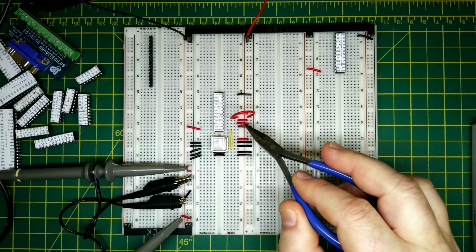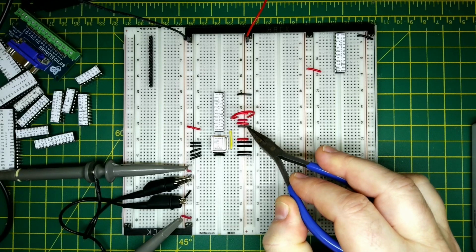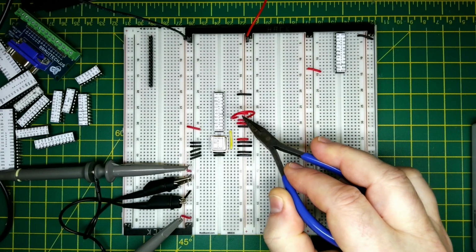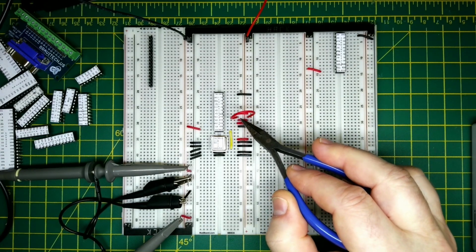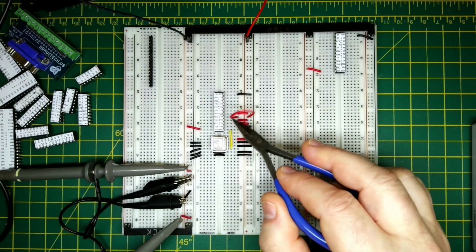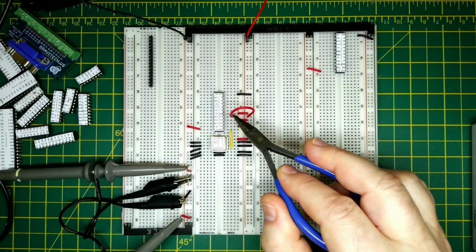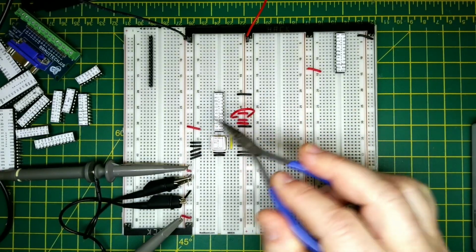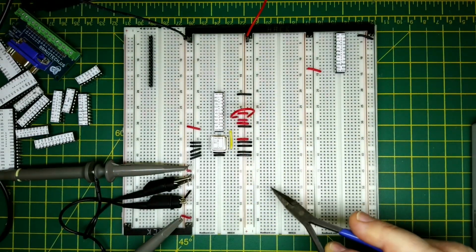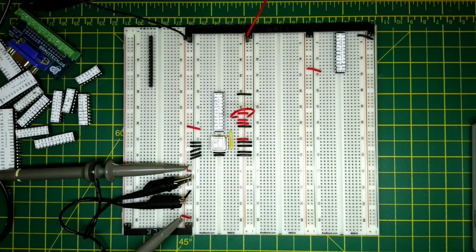One of the outputs is to do with the underline row address, and so what I have done here is wired up the RA0 to 0 volts and all the others are wired up to 1. So I think it was row address 14 where the underline was going to come. At the moment I've just wired that up, so we would expect that to be 1 or high at the moment, and then perhaps if we hook this line up to something that toggles between 1 and 0, then we should see this line toggle, and when we eventually wire this up to the CRTC, then we should see the underline row address go high when we get to row 14.